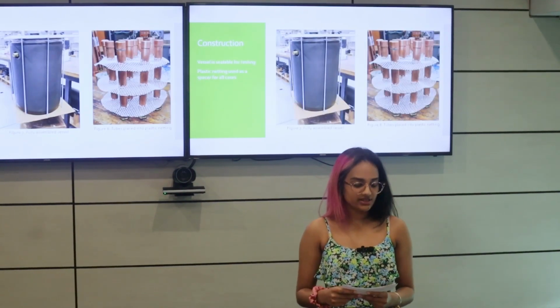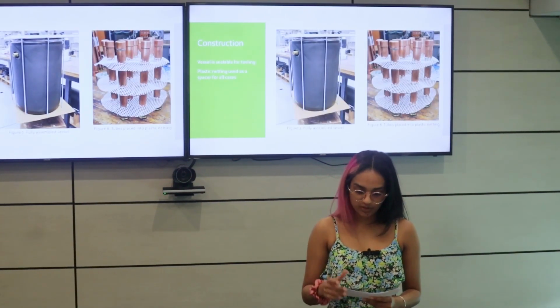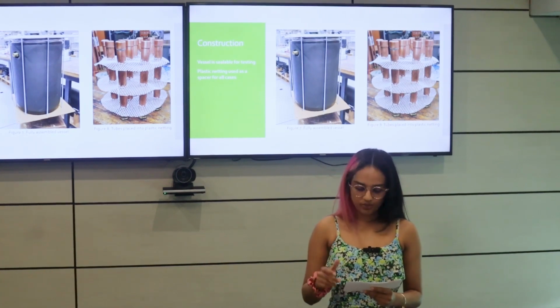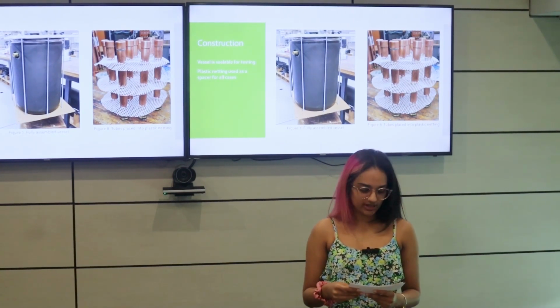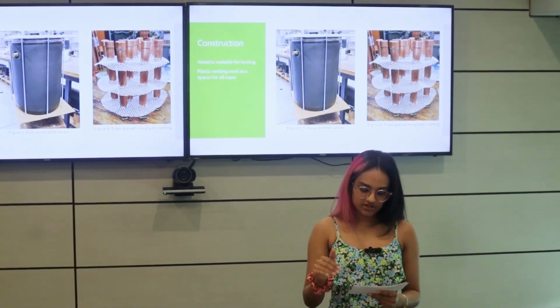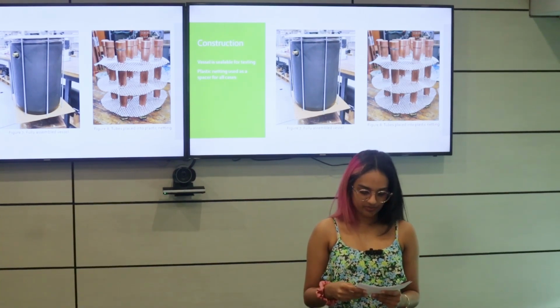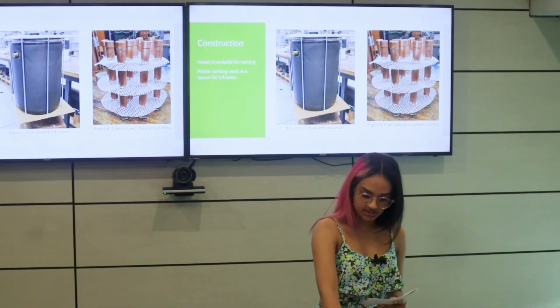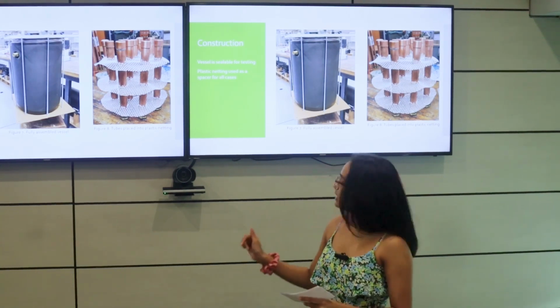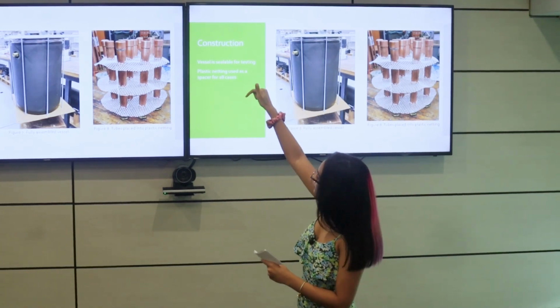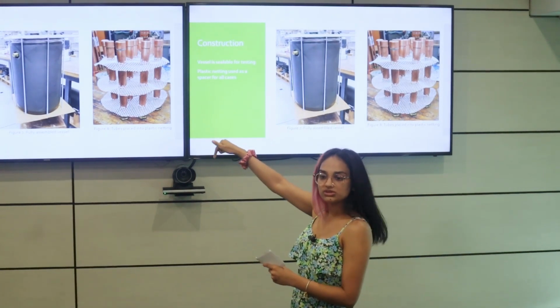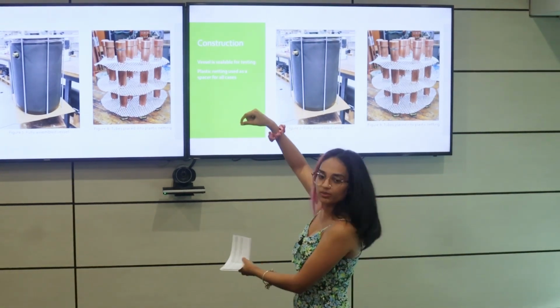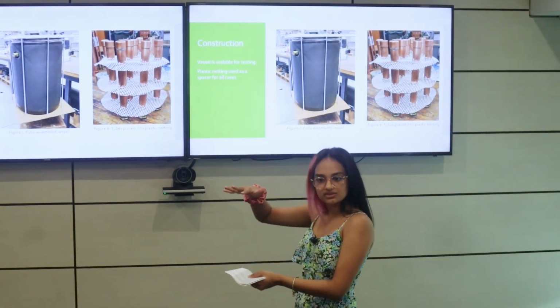In order to seal the vessel, I made a base from silicone-treated chipboard and a lid from acrylic to ensure that I could see into the tank during experimentation. The lid and base are held together by rods and nuts, as can be seen in figure 7. The rods go through the drilled holes, and I have nuts on the top and the bottom that I tighten to ensure that the vessel is completely sealed.